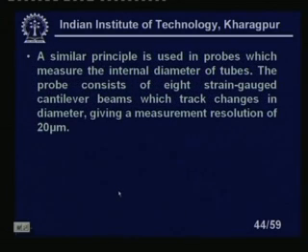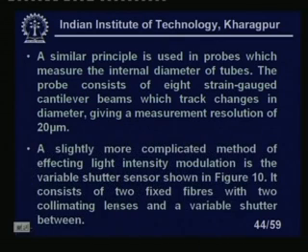A similar principle is used in probes which measure the internal diameter of tubes. The probe consists of a strain gauge cantilever beam which tracks changes in diameter, giving measurements with a resolution of 20 micron, right. So, in many situations we need this.